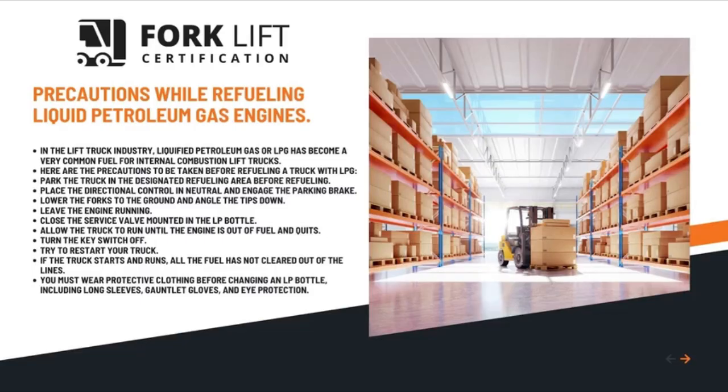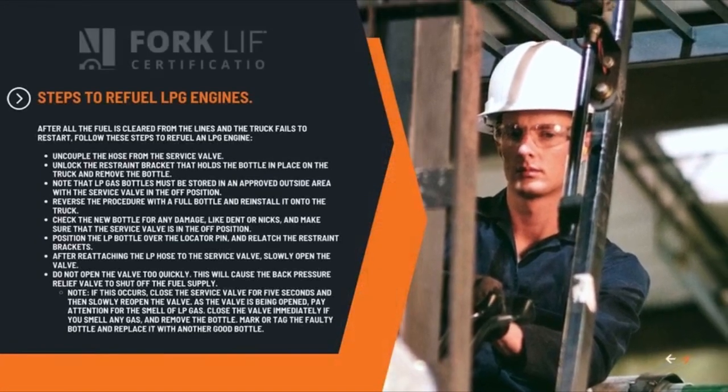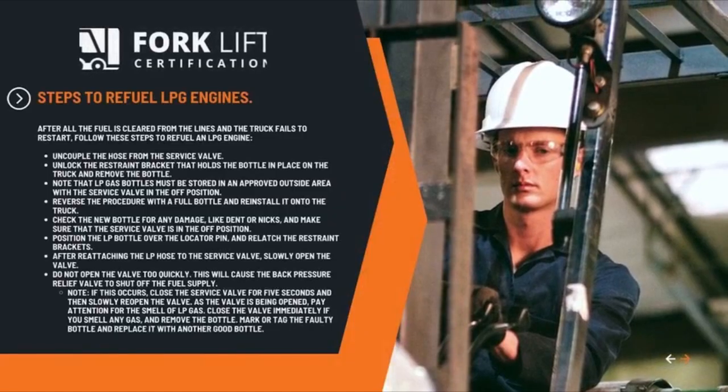You must wear protective clothing before changing an LP bottle, including long sleeves, gauntlet gloves, and eye protection. Steps to refuel LPG engines. After all the fuel is cleared from the lines and the truck fails to restart, follow these steps to refuel an LPG engine. Uncouple the hose from the service valve.